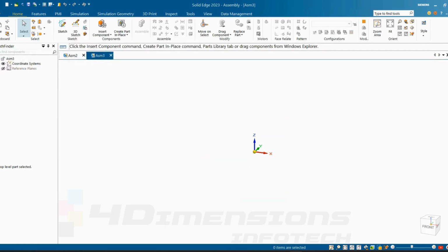In the assembly interface, this icon is a little bit different. Instead of orange lines, you can see the orientation of these three boxes has been reversed and there are three blue lines. So this icon represents assembly of Solid Edge. And this icon, you can see here, three simple boxes in 2D with an orange line, represents the weldments.